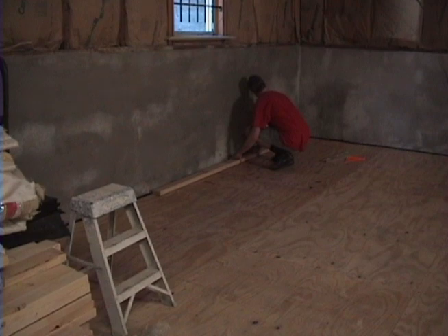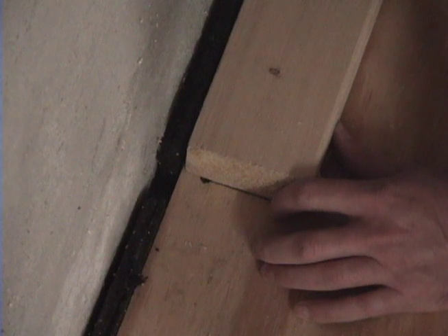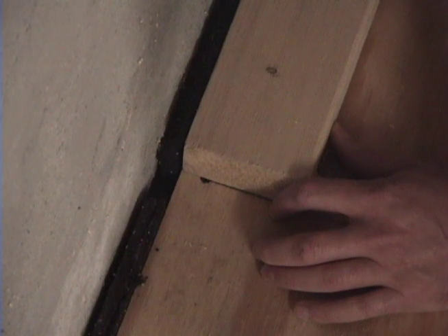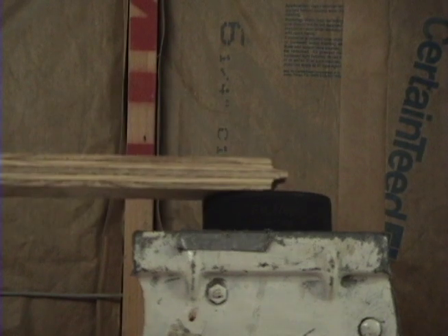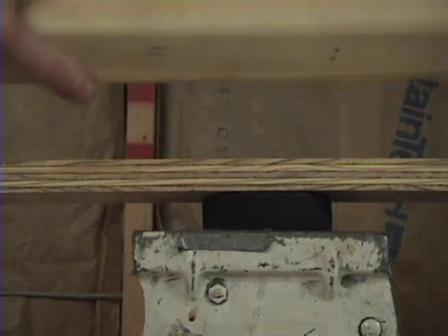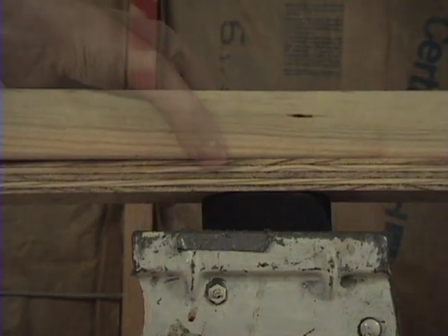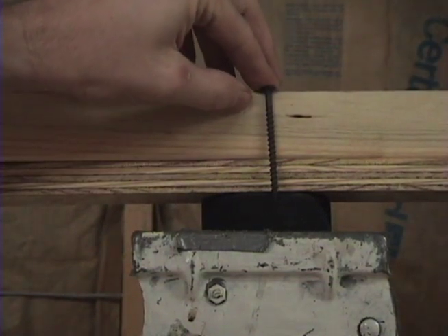In my particular case, I know the back wall will not move, so I'll start by setting the bottom plate in place for the back wall. Remember that we use concrete expansion joints for isolation from the concrete wall of the existing structure? The expansion joints are also a guide for our bottom plate placement. The idea is to use a screw that is long enough to go through the 2x4 bottom plate and the subfloor and possibly into a hockey puck, but it's not so long as to go into the concrete slab.